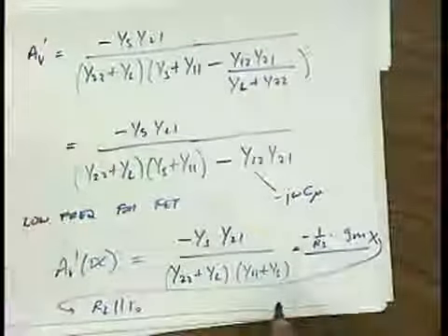If I divide everything out here, this Ys over Y11 plus Ys is simply Zin divided by Zin plus Zs. So of course this is a trivial result again, so let me take this out. This is just telling us that at low frequency the gain is minus Gm times Ro in parallel with RL times some voltage divider. That's trivial. Okay.